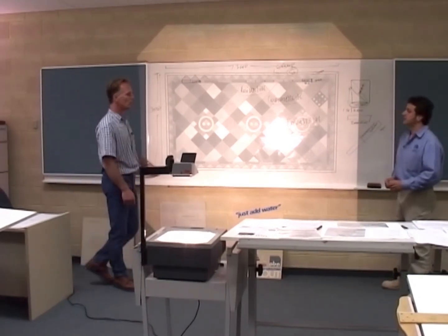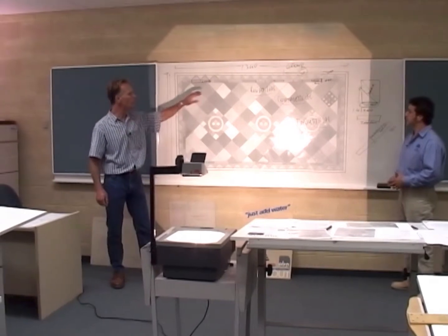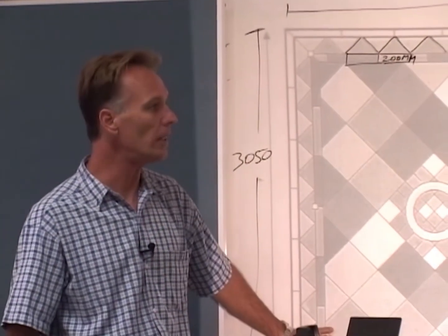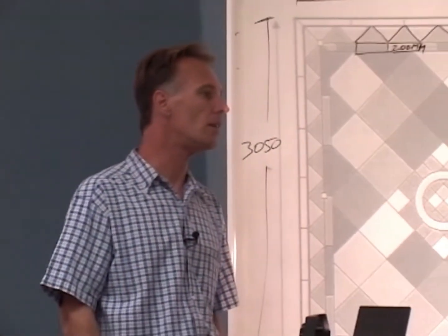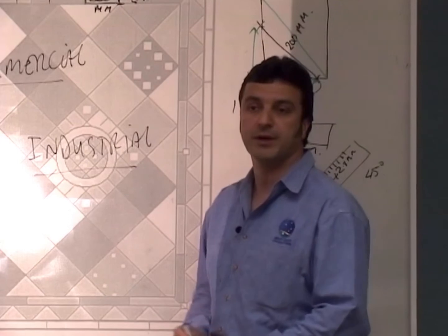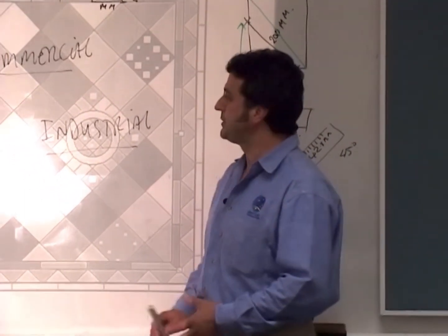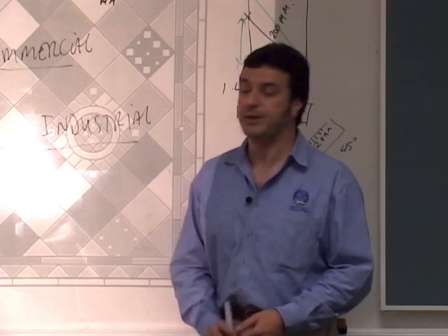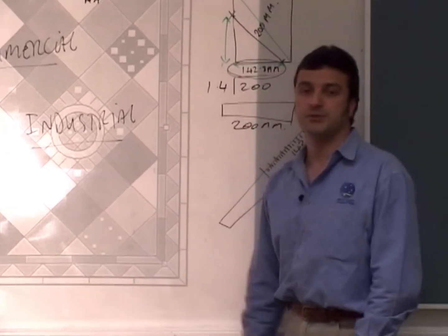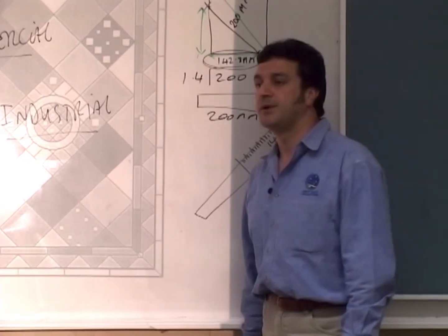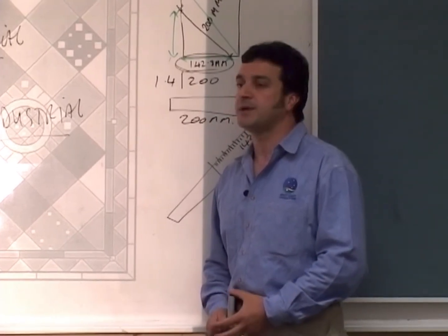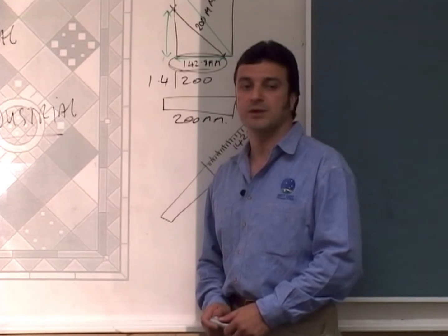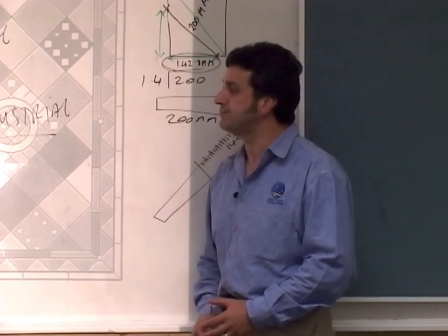Enzo, just a question I've just thought of. With all the cutting involved in such an intricate job, will using the more heavy-duty industrial or commercial tiles affect the difficulty of cutting? It's just going to mean a lot more pressure on the tile cutter as they strike and scribe the tiles, but generally speaking they cut reasonably well. Some of the real heavy industrial tiles may sometimes require diamond saws, especially for some of the diagonal cutting. You can get a few difficult tiles that don't cut as easily as we'd like, but generally it's not a major problem. We tend to get through that situation quite well.